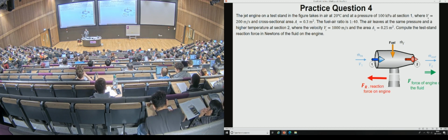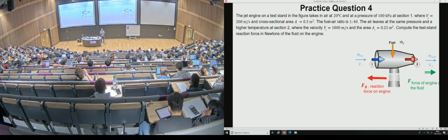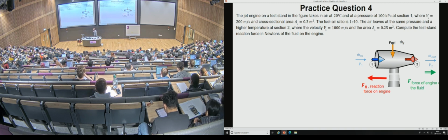You're given the two cross-sectional areas, and you're told that in addition, fuel is added. So this starts to be a little bit more complicated. When we start thinking about cross-sectional areas and velocities and densities, we can immediately think of volume flow rates and mass flow rates. But when we have the addition of an additional source, we have to be careful. And this is starting to go back to this idea that in our control volume, we have to account for sources and sinks, additional sources.